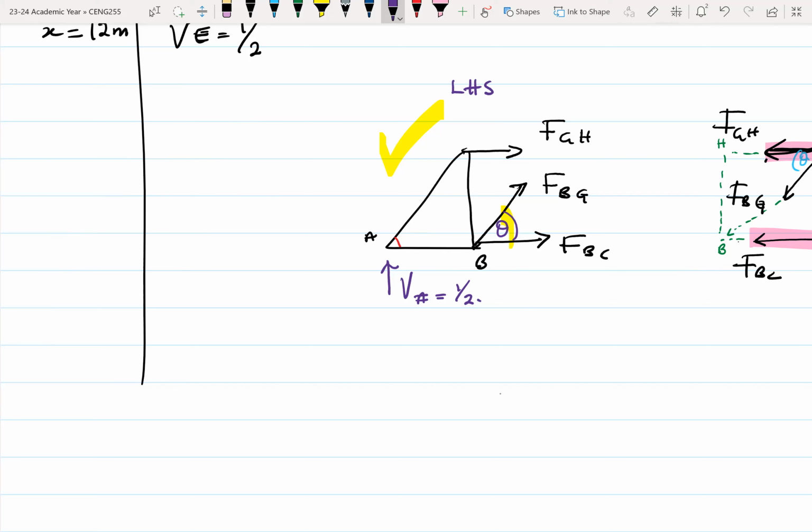By definition, your loads are normally acting downwards, because influence lines are usually drawn for a unit load which is acting downward. Because you have your unit load acting downward, especially on the bridge system, it means that your reactions would act upwards.